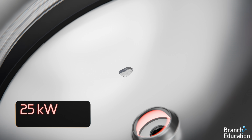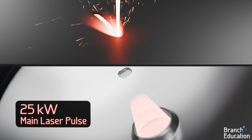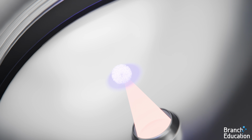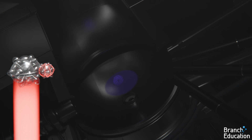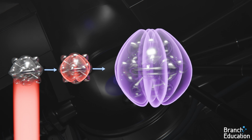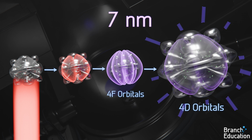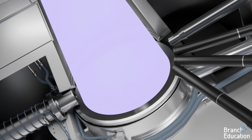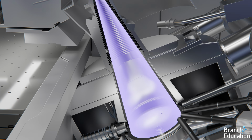The second, approximately 25 kilowatt main laser pulse, which is more than 10 times stronger than the lasers used to cut steel, hits the tin pancake, instantly vaporizing it and turning it into glowing plasma. Within each of the tin atoms, some electrons are ejected and others are kicked up to higher energy states. When electrons drop back down from the 4F to 4D orbitals, 13 nanometer EUV light is produced. Shooting two laser pulses at a droplet of tin might seem like a rather obscure process.